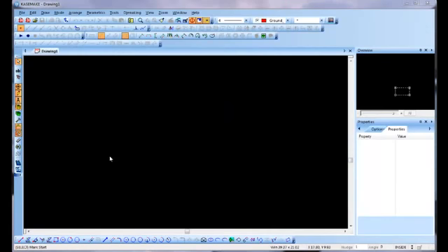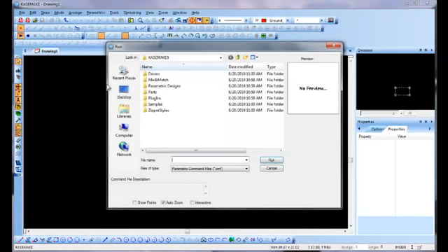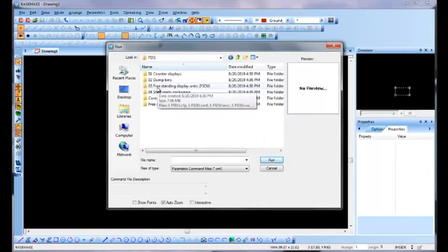very powerful tools within KASEMAKE. They can be used to make layouts for POP displays or packaging designs. To start a parametric, we go to our parametric toolbar, click Run. Then in the KASEMAKE folder, we'll go to Parametric Designs. We'll go down to POS, and for the purposes of this demonstration, we're going to go to Freestanding Display Units.